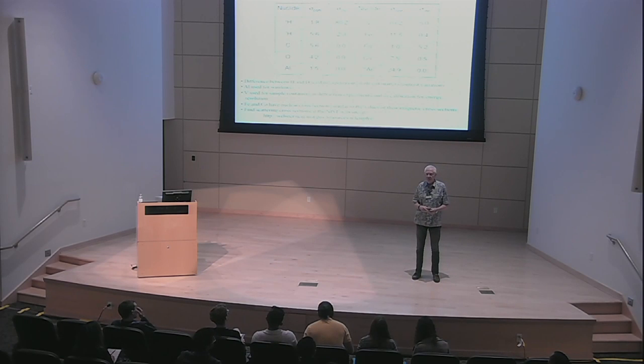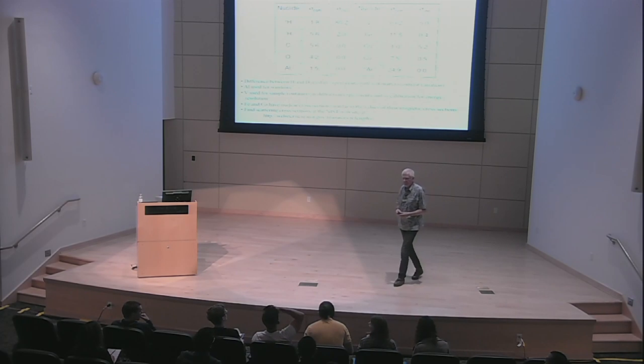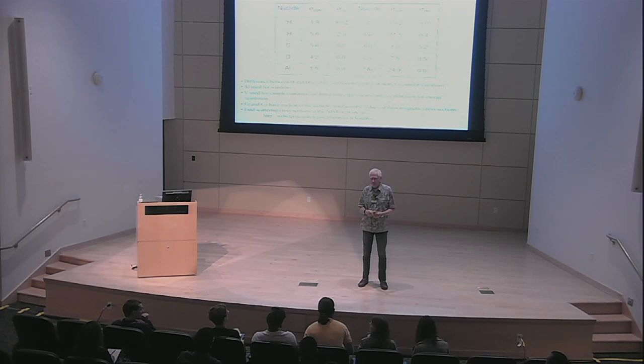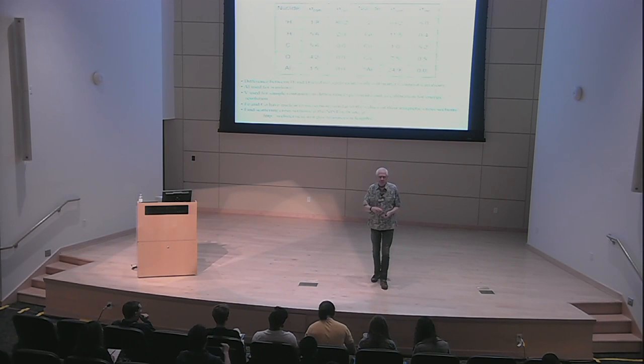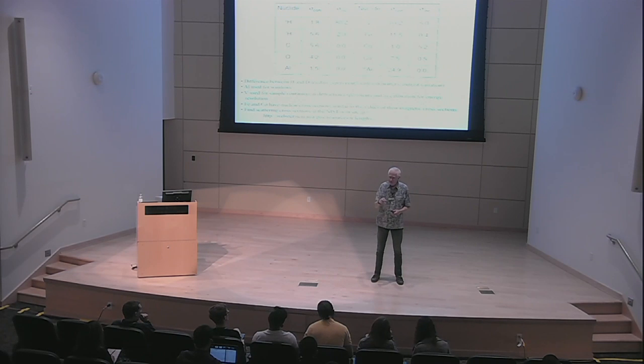Other questions? Yeah? What was the B and H field that you mentioned yesterday? So when you apply, let's talk about a current in a loop, right? That produces a field H, which magnetizes a material. So then you have the total B field, B equals mu naught H plus the magnetization.